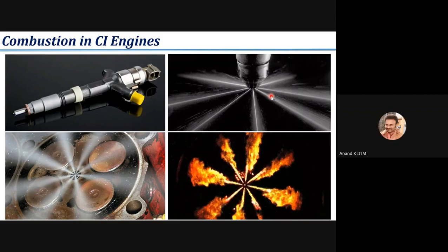Latent heat, sir. Latent heat. You need latent heat to convert liquid phase fuel into gas phase, and that latent heat is taken from air. So you have a significant proportion of air inside the cylinder. When you spray fuel, the fuel particles take latent heat from air and get converted to gas phase. So this is what is vaporization.